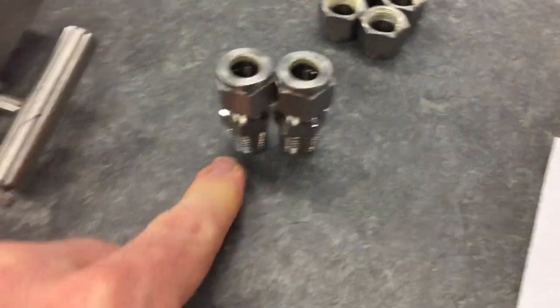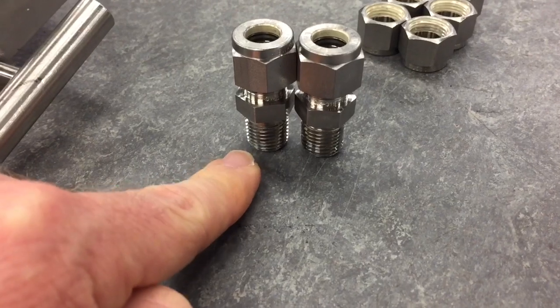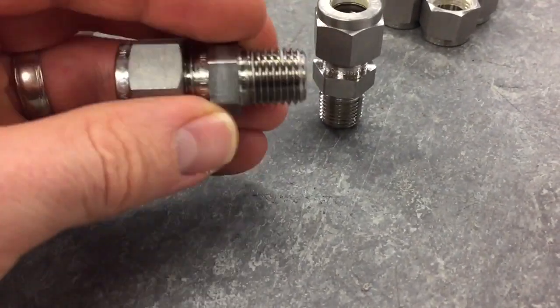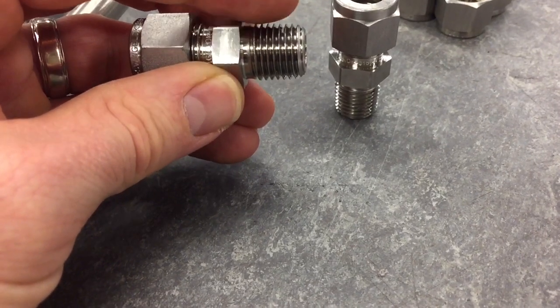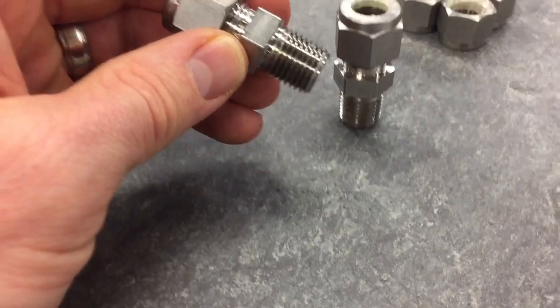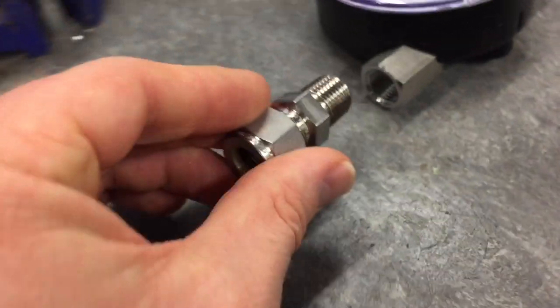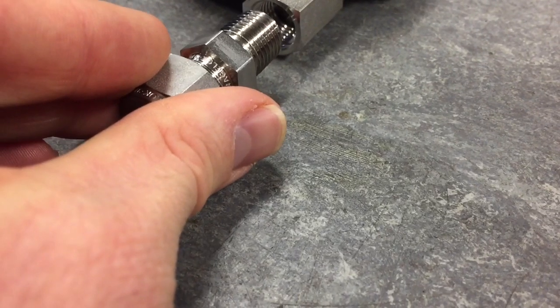The next thing I want to demonstrate is putting the Teflon tape onto these fittings here. It's very important that we put Teflon tape onto these fittings. It kind of helps a little bit with the sealing, but also importantly, it lubricates the threads, the Teflon does. So then if we ever do, you can see here, we're going to be threading it into right here. If we ever do need to remove this fitting, we can.